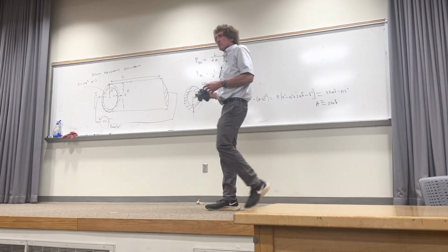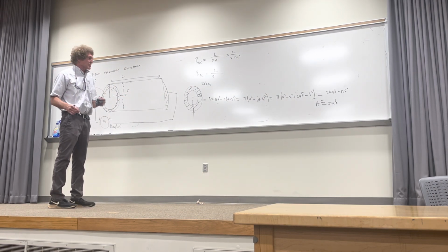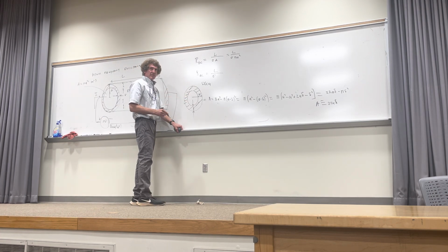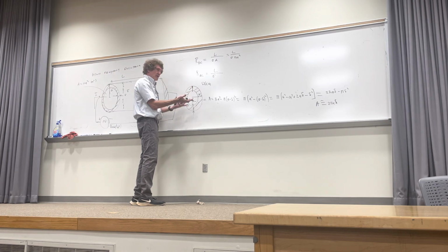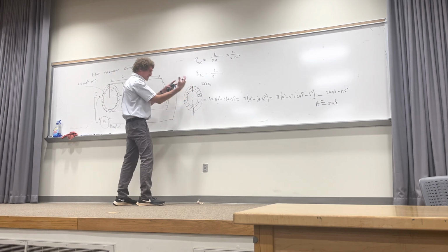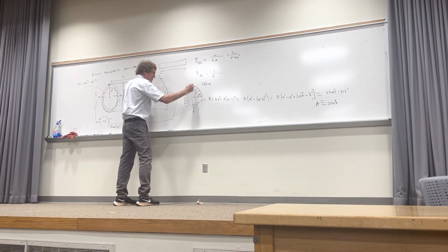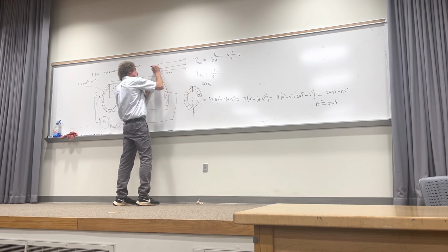And let me make this a little more apparent so you don't have to worry about formulas all the time. Think of it this way. If you have this geometry, if you cut it right here, and then you simply stretched it out and laid it flat, it would look like something that had the actual circumference and length, which would be 2 pi A, and would have a thickness of the skin depth.